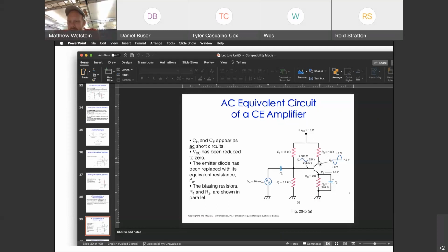And you'll notice that if I were to take this point off and do a DC, when the base current swings up, this current actually swings down from whatever it was with respect to 15. And when the base current swings down, then I'm subtracting less off of 15, so this voltage swings up. So there's a sign flip to note there.